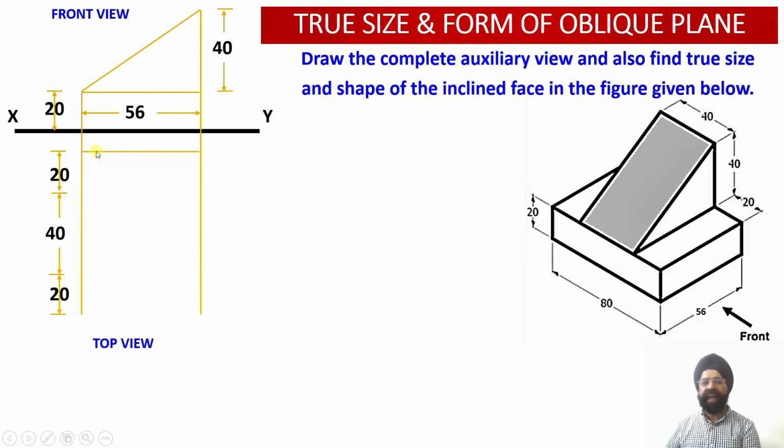Now I can draw horizontal lines corresponding to this portion. So this rear edge of the solid has been drawn over here. Then the second edge, this edge corresponds to the section surface over here, that is edge number 2. So I can plot it over here. Then this is edge number 3 corresponding to the second edge of the section surface. So edge number 3 has been plotted. And finally we have this front edge of the solid, the edge number 4, which will be plotted over here. So with this we have completed the construction of the front view and the top view of this particular solid.